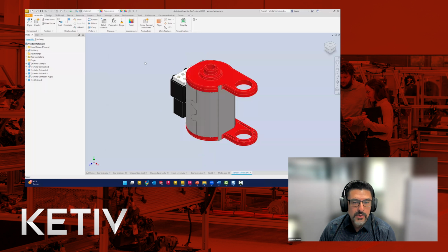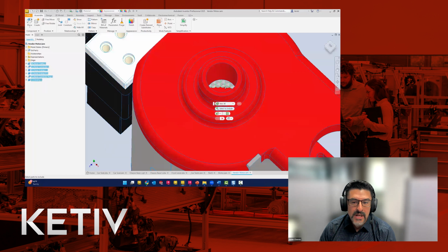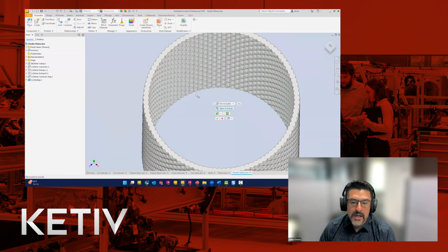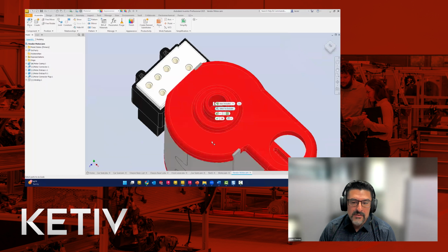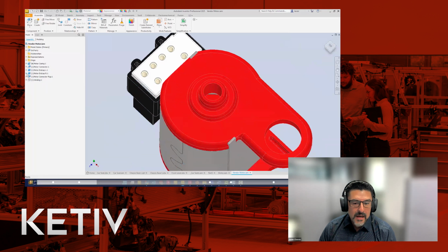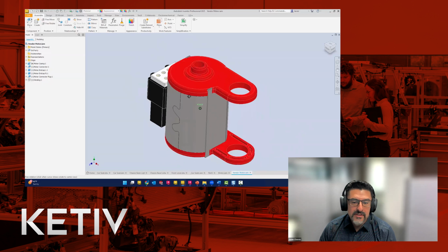We're going to use a series of tools, and within the assembly environment, you could start editing what you really want to maintain in this assembly. And so that internal component, when I launch it, I could pick that edit view tool to say, do I want to include it? Do I want to exclude it? I could change my view to see what's excluded, and that's what we're going to take out. And simply by clicking OK to that, on the left-hand side, you can see the winding is now turned off. So step one in simplification, get rid of stuff you don't need.